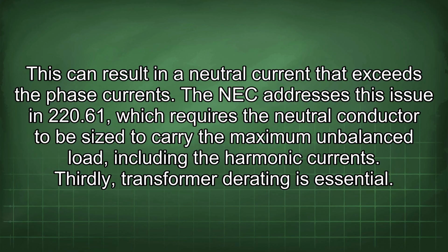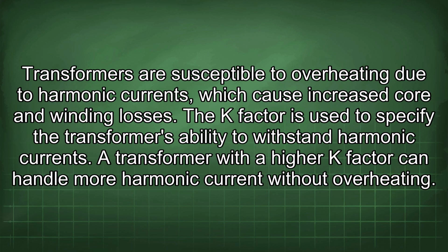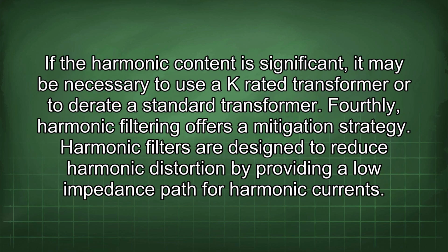Thirdly, transformer derating is essential. Transformers are susceptible to overheating due to harmonic currents, which cause increased core and winding losses. The K-factor is used to specify the transformer's ability to withstand harmonic currents. A transformer with a higher K-factor can handle more harmonic current without overheating. If the harmonic content is significant, it may be necessary to use a K-rated transformer or to derate a standard transformer.